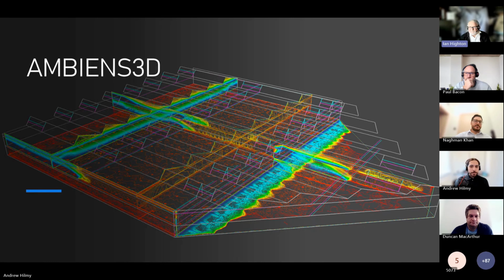So this is leading on to the next step where we can actually take the building simulation results into the CFD, which Duncan mentioned a little bit previously. This is going back a few years now, but the ambient solver has 5 unique features. It implicitly conserves mass without having to use the pressure correction processes, which clearly hugely improves stability. One thing I haven't mentioned is that we've got quite a good CFD validation page on our website, with lots of standard cases. So that's worth a look if you get a chance.